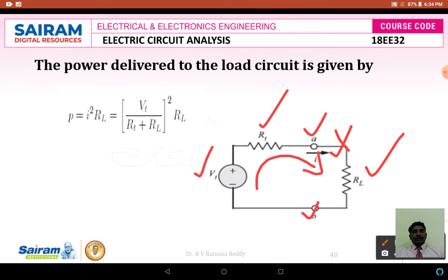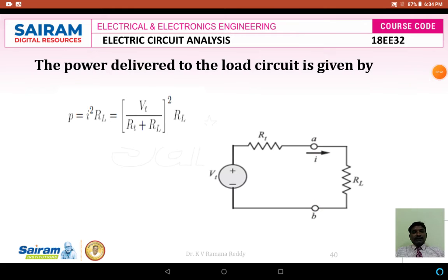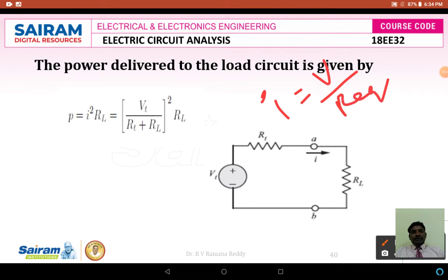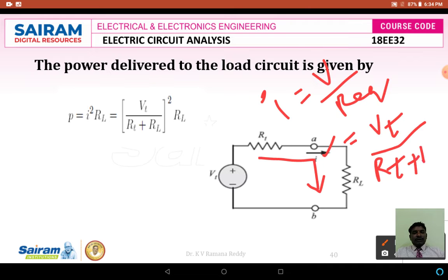Mathematically, what can we express for I? I is equal to V by R equivalent. Here V is Vt, the Thevenin's voltage. R equivalent: RT and RL are both connected in series, because only one current flows in this one loop circuit, that is I. Therefore, in place of R equivalent we can write RT plus RL.